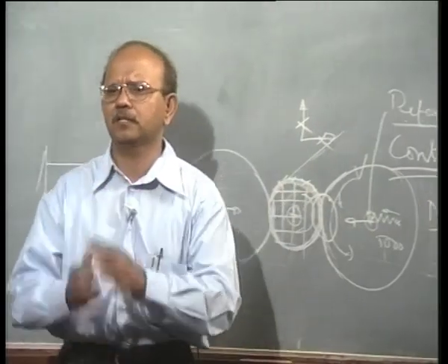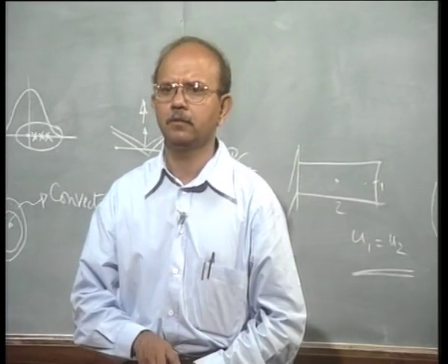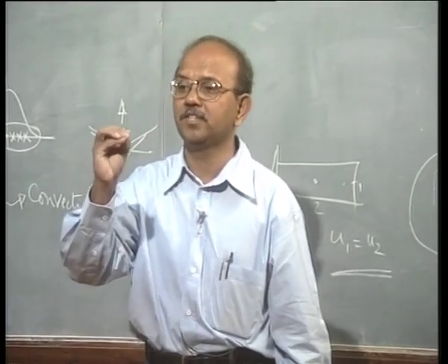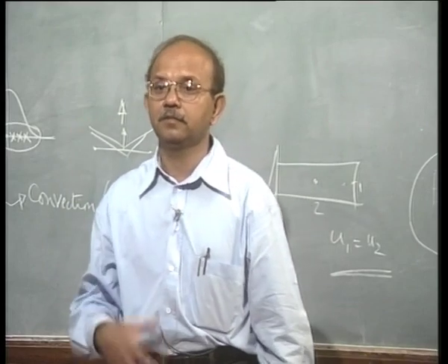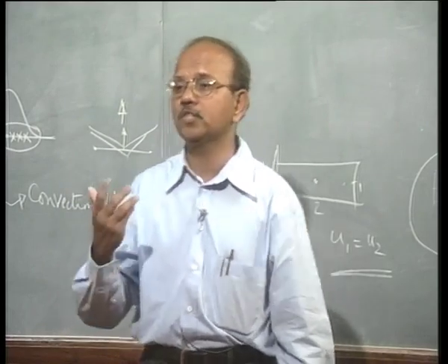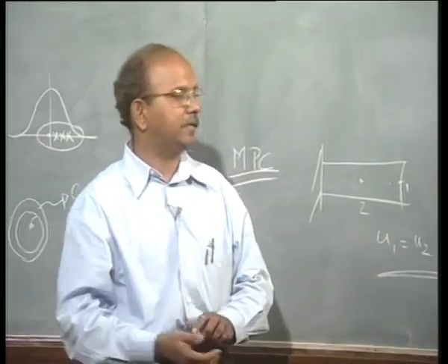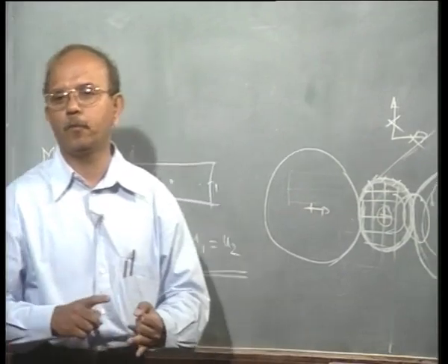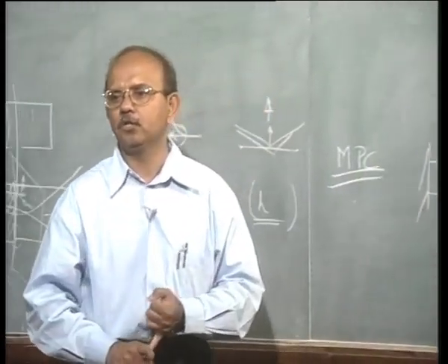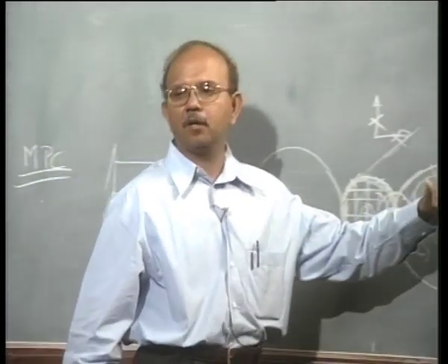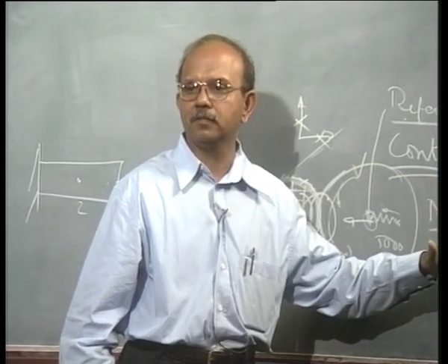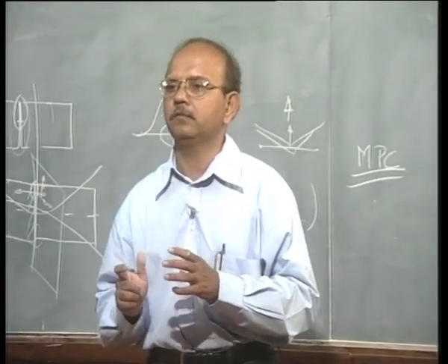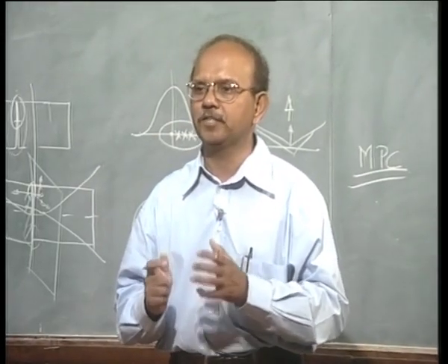Many softwares ask which is the master, then you say that this rigid surface is my master. It also asks for your slave set, then you say that these nodes here are my slave set. So point number 2, when you use contact, you define a master surface or master node set and a slave node set. Point number 3, this contact algorithm develops a stiffness matrix.